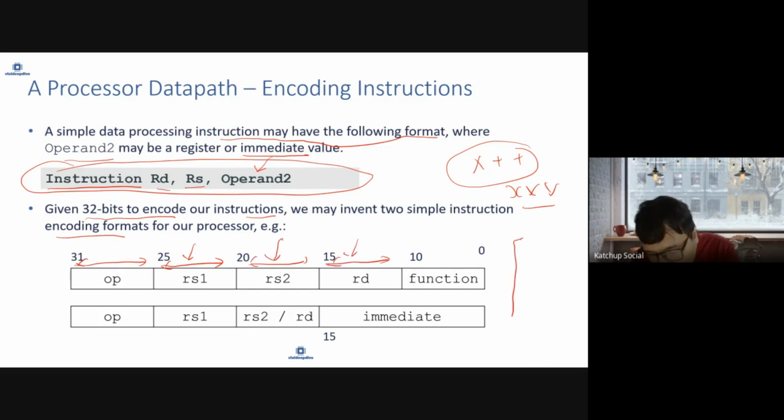If you remember, we had our register file which is 32 deep. So we are keeping 5 bits each for storing the address of the result, the address of operand one, the address of operand two, and then you have the function. Sometimes the opcode can be the same, since the opcode decides what operation you are going to do, and then additional information is given in the function field to do that operation. This is the case when two operands are different.